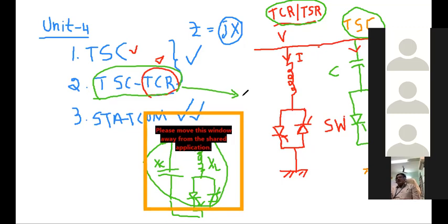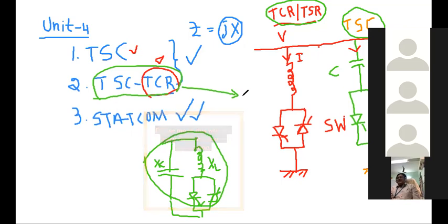Okay, then we do this one: by changing the excitation, we note down the current values and power factors, and we draw the graphs between field current, armature current, and the power factor. We draw the V and inverted V curve.